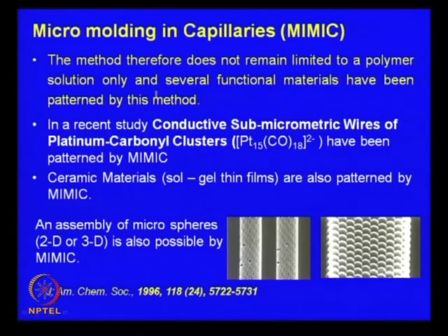Several functional materials, including dispersions, which is very important, colloidal suspensions, etc., have also been successfully patterned by MIMIC, which is one of the key advantages of this technique. There has been a recent study of conductive submicron wires of platinum carbonyl clusters, some complicated stuff. You do not have to worry too much about the chemical composition, these have also been patterned by MIMIC.